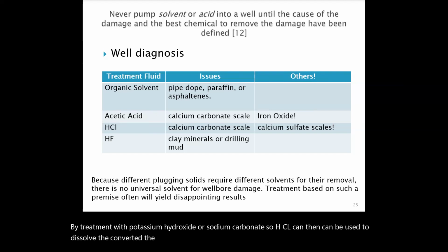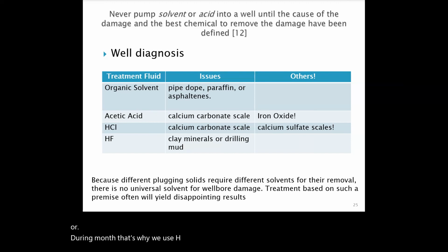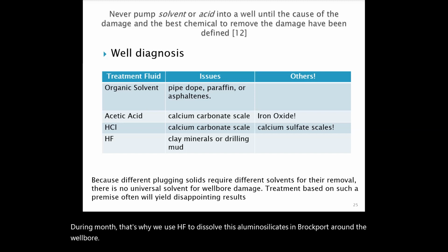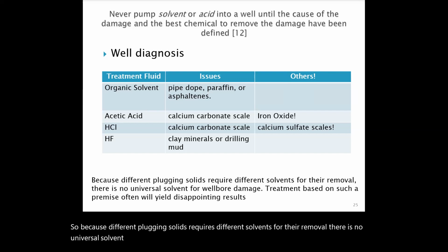Calcium sulfate also can be dissolved in one step with the sodium salt of ethylene diamine tetraacetic acid, or EDTA. HCl will not dissolve formation clay minerals or drilling mud. That's why we use HF to dissolve these aluminosilicates in rock pores around the wellbore. Because different plugging solids require different solvents for their removal, there is no universal solvent for wellbore damage. Treatment based on such a premise often will lead to disappointing results.